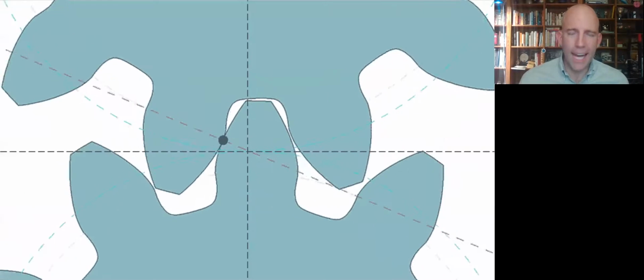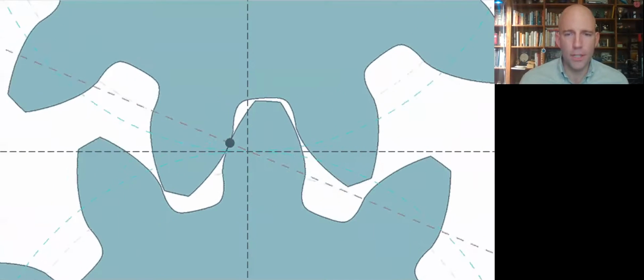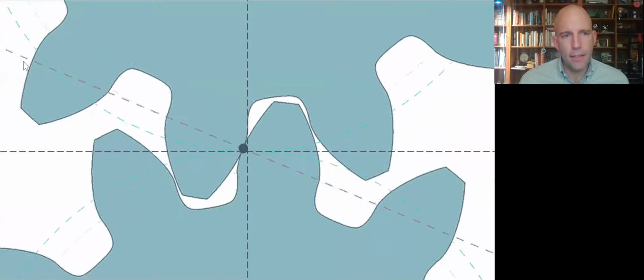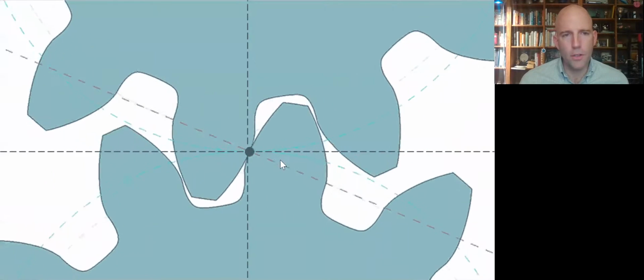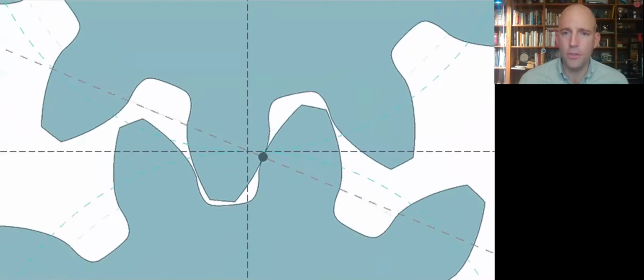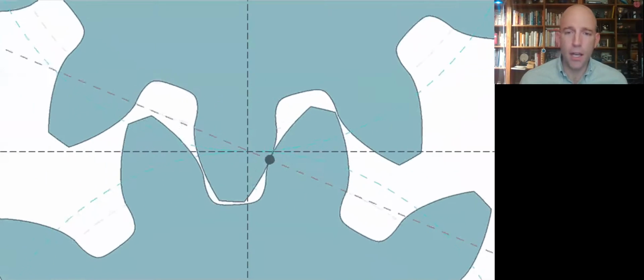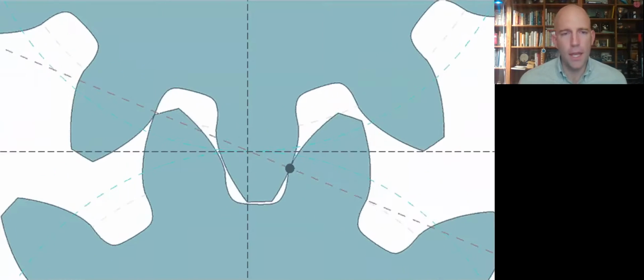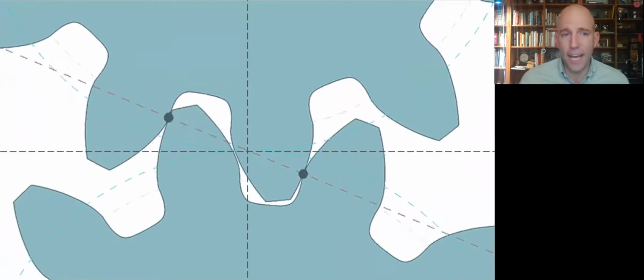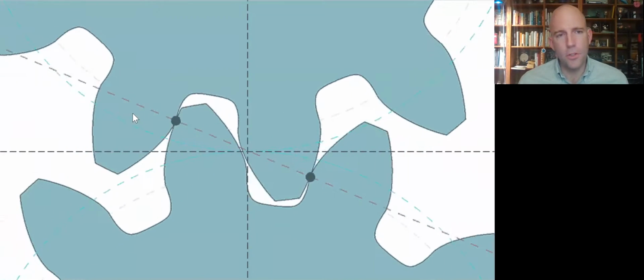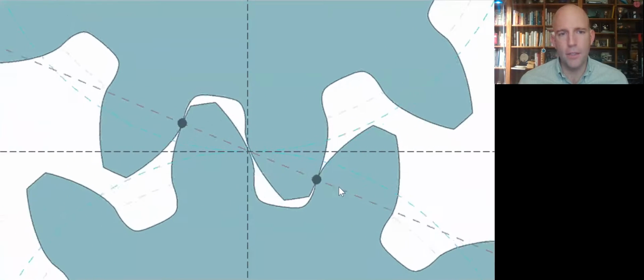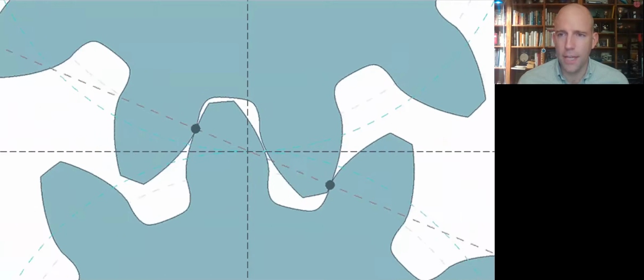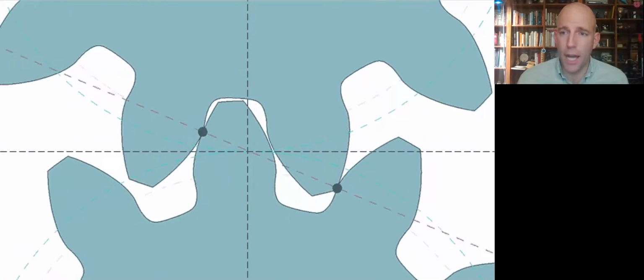And we'll see that the contact between the teeth moves on a line. And that's that line we were talking about earlier that is normal to the tooth surface. And that's because of this special shape of the teeth, this involute shape. And that actually is defined by trying to get the contact between the gear teeth to move along this line. That's how you derive the involute shape.